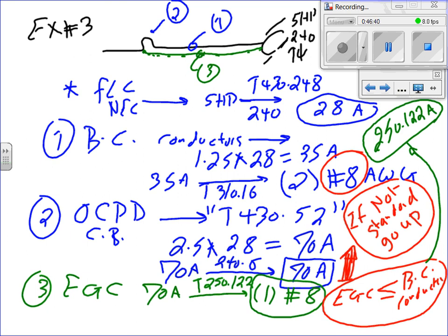And this is how we size the overload. The overload is sized not coincidentally. Look, the conductors are sized with what? With 25% extra, right? When we size the overload, we size it up to 25% extra. Sometimes 115 or 125. No more than 125. So when you size your overload protection, you size it based on a maximum of 125.